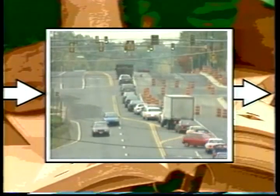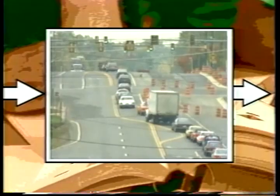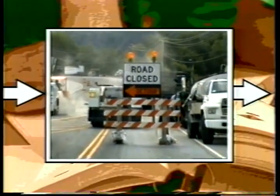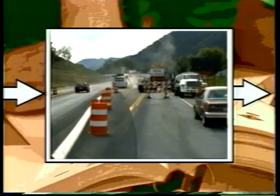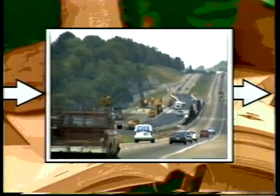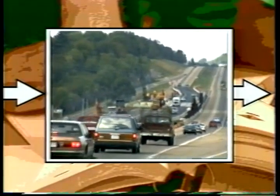For the 3rd step, they must identify which strategies may be appropriate for this work activity. Strategies include lane width reduction, lane closure, median crossover, temporary bypass, detour, intermittent lane closure, and use of shoulder or median.